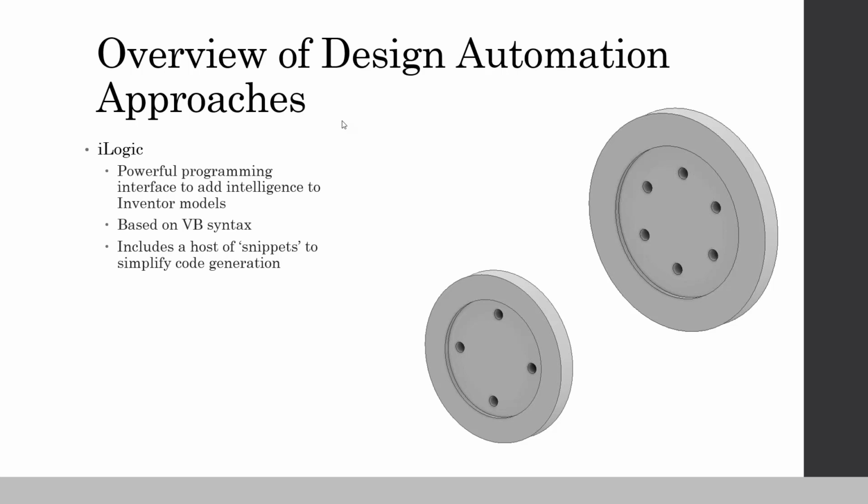And technically, there are some things you can do with features in default Inventor, but it can be a lot more transparent and a lot easier to do those things and change those things with a simple iLogic rule. And these rules, it's basically just some code that usually lives in a part or drawing. It can also be external to the document. I'm a big fan of keeping things internal to documents where you can, because then you don't have to worry about, when you migrate, where did this rule go, and do we need to reconfigure Inventor to point to the special folder, right? If you can put the stuff in the document, so much better.